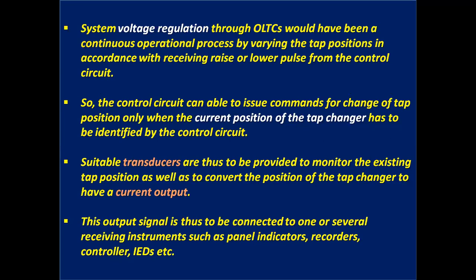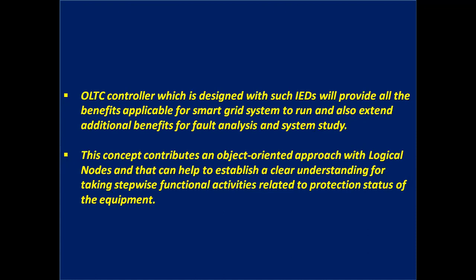The output signal is thus to be connected to one or several receiving instruments such as panel indicators, recorders, controllers, IEDs, etc. The OLTC controller, which is designed with such IEC, will provide all the benefits applicable for a smart grid system to run and also extend additional benefits for fault analysis and system study.